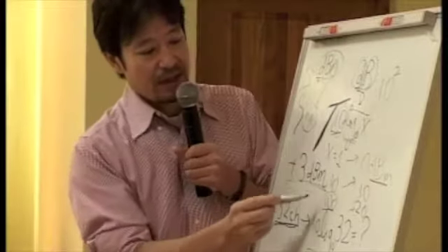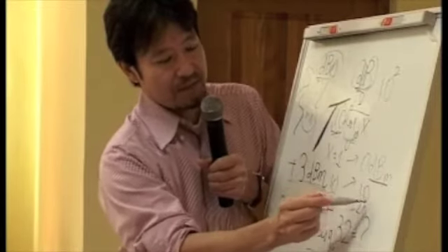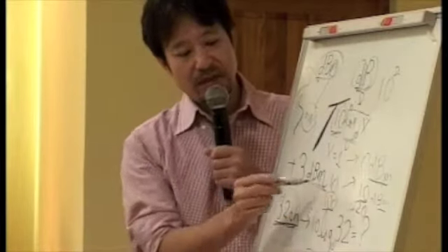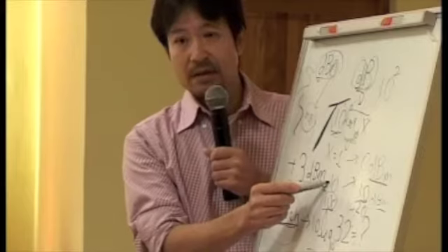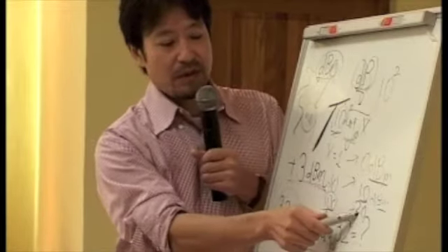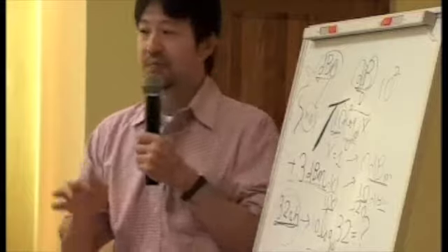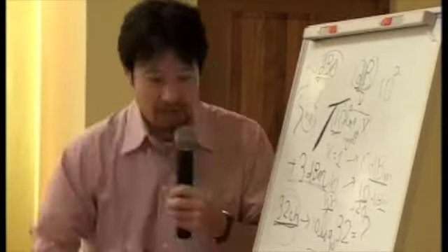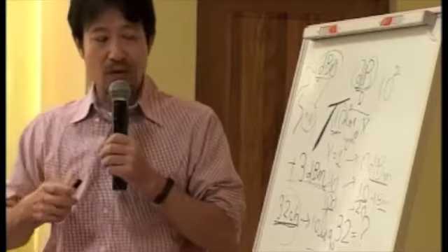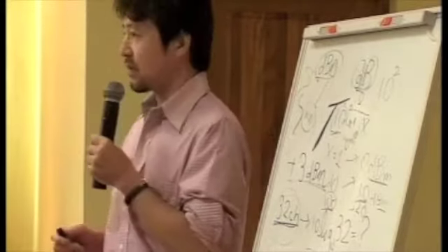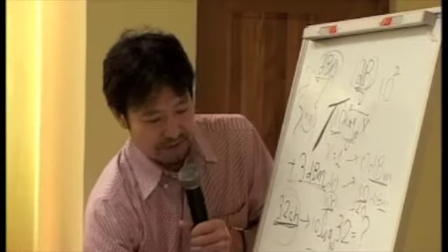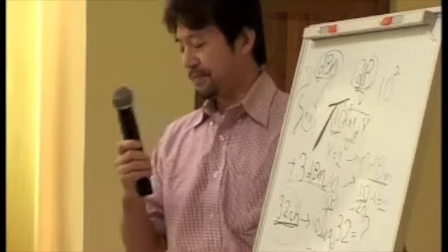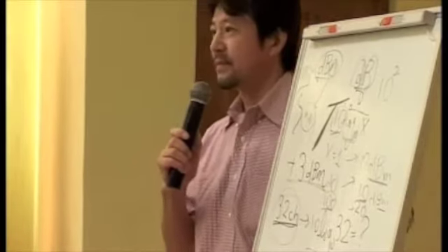If we say 10 dBm, not dB, that means 10 milliwatts. And 20 dBm means 100 milliwatts. This is dB or dBm, so often used in the field of optical communications. So I'd like to confirm these things before the tutorial. Thank you. Any questions? No?